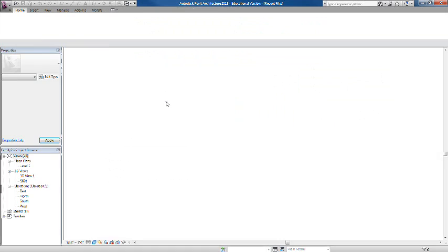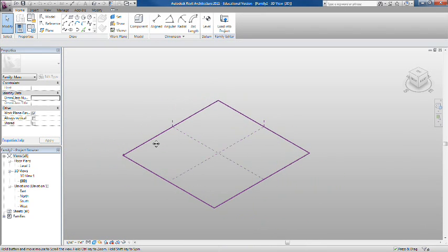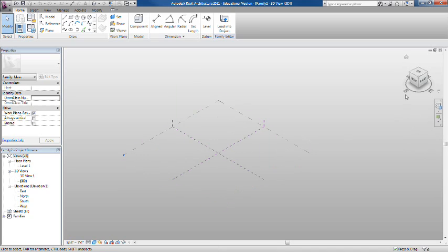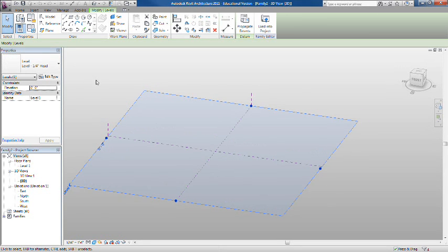On SketchUp components, there's no need to do adaptive components because none of the options are adjustable once you get the model into Revit from SketchUp. That only works on components actually made in Revit.